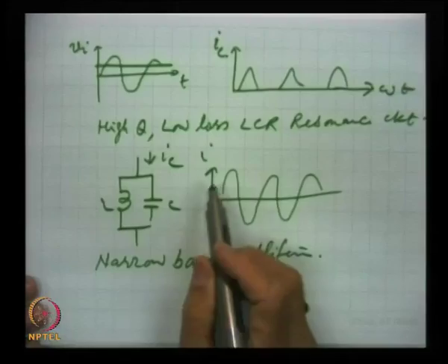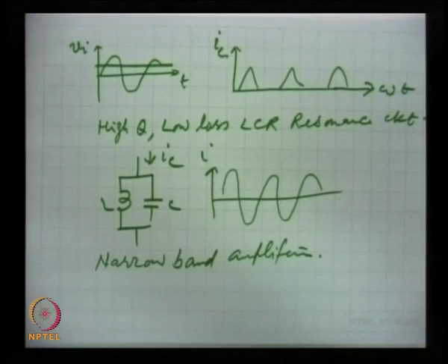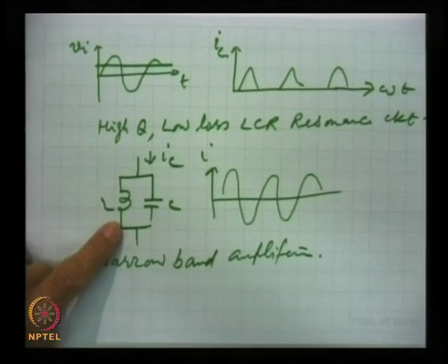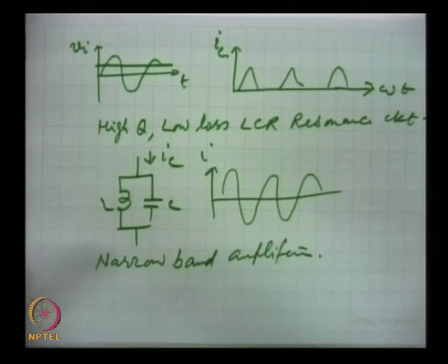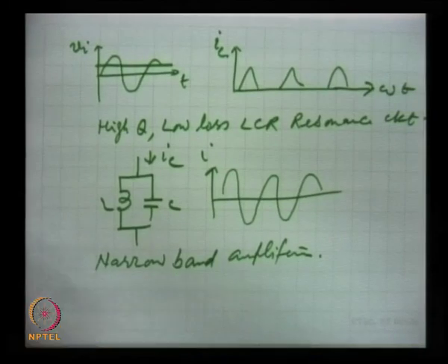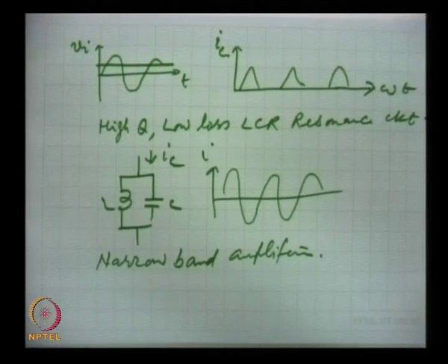High power carrier waves are to be generated, their efficiency will be a big consideration, and in class C amplifiers the LCR circuit is tuned to the carrier frequency, and this is the part of the class C amplifier, and from here the high power pulses will be transmitted. So, this is the classification of amplifiers: class A amplifier, class B amplifier, AB, and class C amplifier.